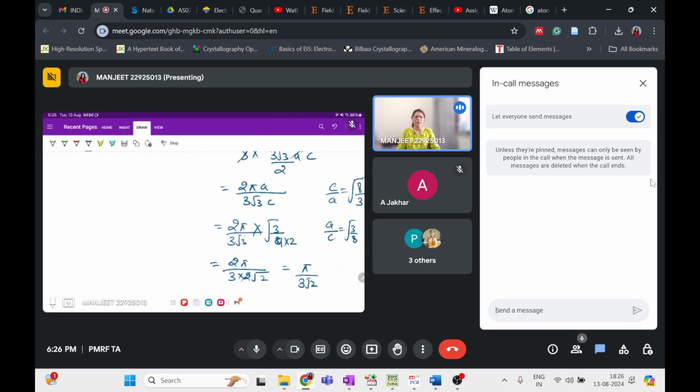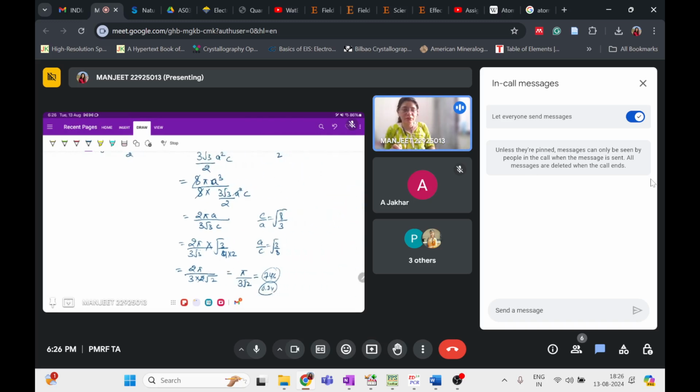And if you calculate it, it will come out that the APF will be 74%. Okay, calculate this value. It will give 0.74, and if you calculate in percentage, it will give 74%. The same thing we can do for the simple cubic, the BCC and the FCC.